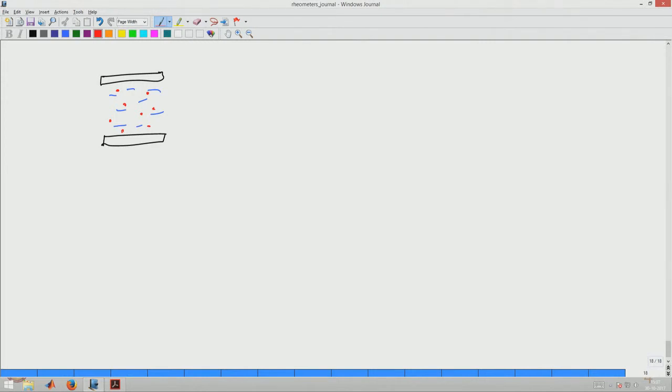We can measure the velocity that way, and if we see that the velocity is what we expect in terms of a linear velocity profile, then we say okay, there are no artifacts in terms of flow being different from the linear velocity profile, therefore we can do the analysis. But if using the particle motion we find that some particles are moving slowly while other particles are moving fast, then we basically have banding in the material.